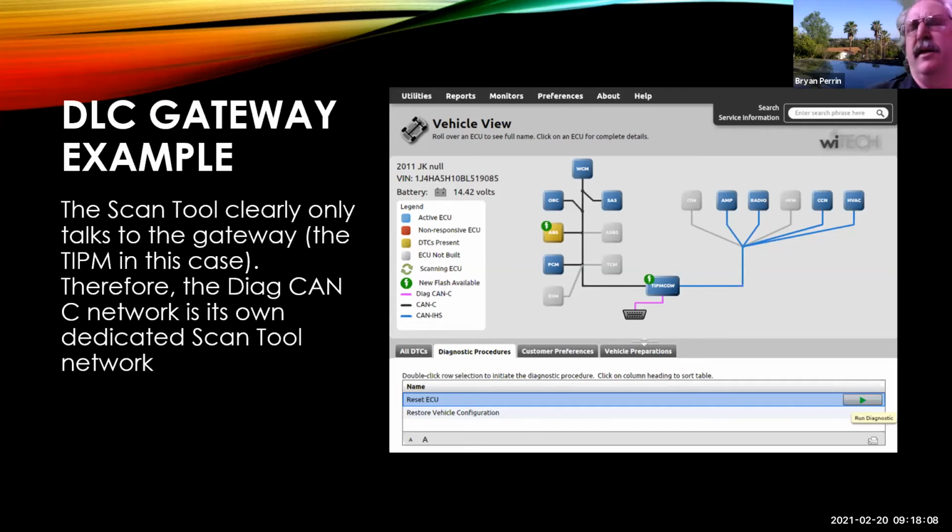Yeah, it shouldn't have done that, but weird things happen with networks, and some things aren't always how they should work. I think it was just mostly voltage. It was a short putting voltage on one of the CAN lines or something. Yeah, and we've done that. We put voltage on the CAN line, and it's definitely taken down the network, but we haven't seen it go through a gateway or cause a gateway that's talking on another network to stop talking.